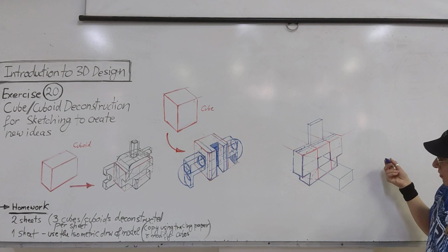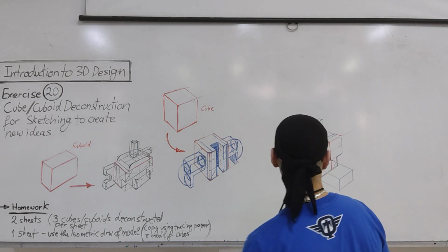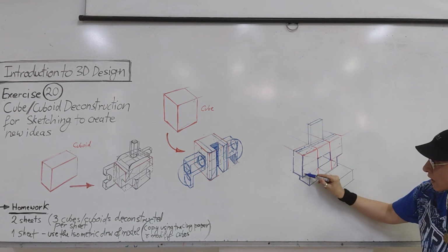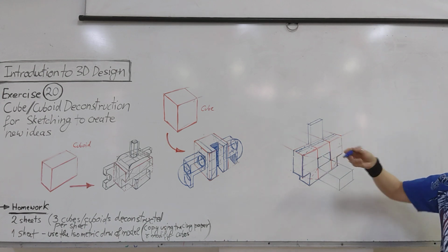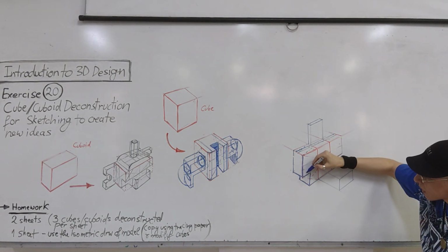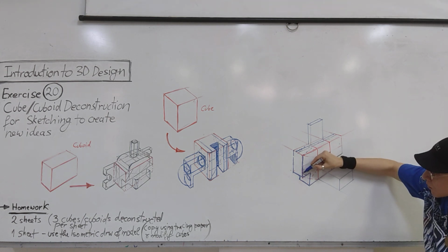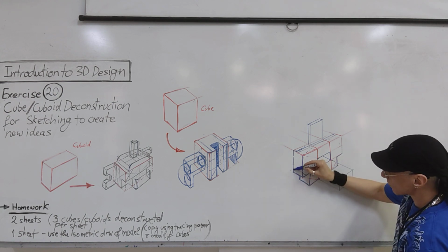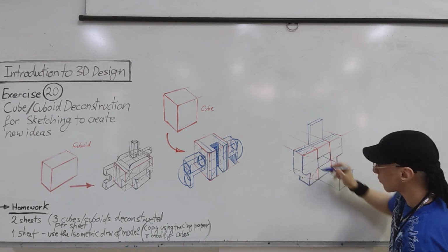Okay, but let's say I want to make now a curve somewhere, okay? Because we have everywhere straight lines, and we want to add somewhere some kind of a radius. Let's say, where shall we add the radius? If we want to add it here, for example, or here, or in this part. Now, what is the size of the radius? Proportionally, what you want to do. So if it's a small radius starting from here, ending here, okay, then I will define it. This point will go to the vanishing point, so we know where the other one will start. So here the corner will be removed, here the corner will be removed.